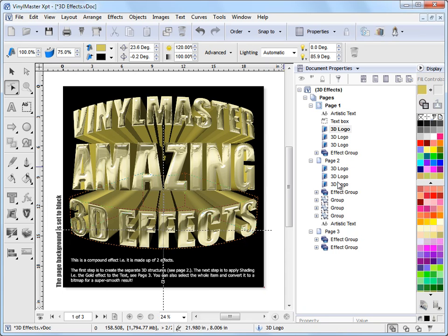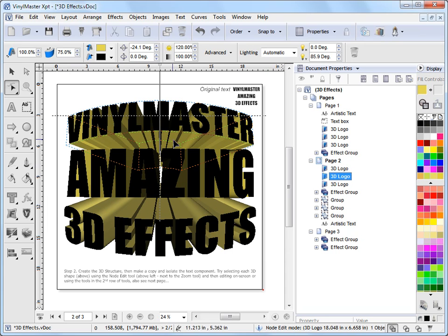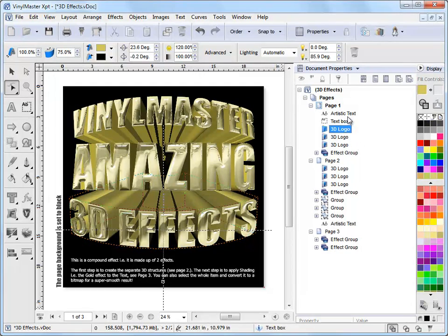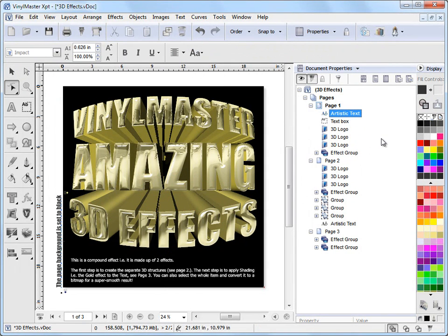That's why this keeps changing here, because it's seeing what you're doing and dynamically changing along here. And I can go through and select other things here on different pages, as you can see. So that's the advantage of the Object Manager. I can move things, their Z order, by moving them around, and I can view things, and I can select individual objects, which means that when I've selected it, I can then go in and edit it. So that's a handy thing for you to know.